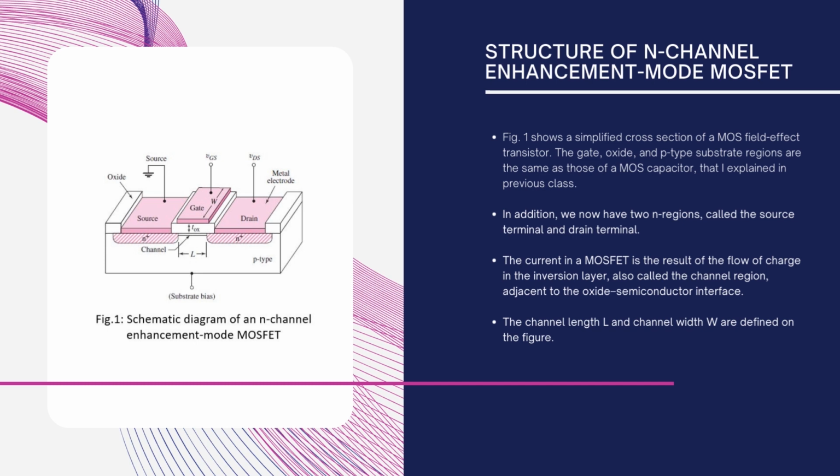Here we can see that the source and the drain are symmetrical in nature. This is a very important aspect of MOSFET formation, that the source and drain are symmetrical. We can exchange source and drain in any device. This gives ample space for fabrication. Therefore, this is one major aspect which allows high density in a small area, because this device is symmetrical.